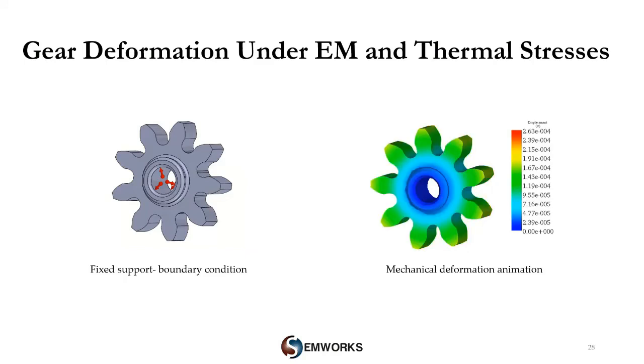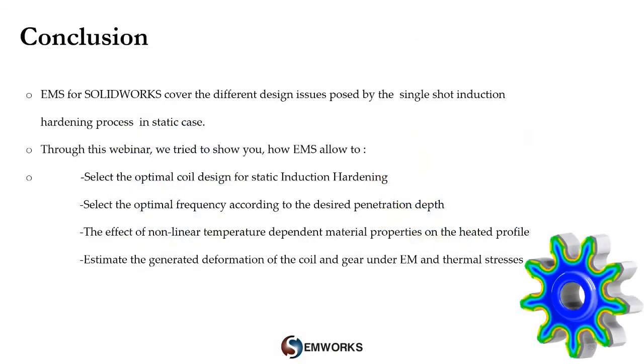Now we conclude with those results. To summarize, EMS for SOLIDWORKS covers the different design issues posed by the single-shot induction hardening process in static case. Through this webinar, we tried to show you how EMS allowed to select the optimal coil design for static induction hardening and to select the optimal frequency according to the desired penetration depth.